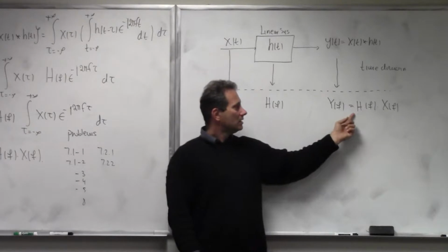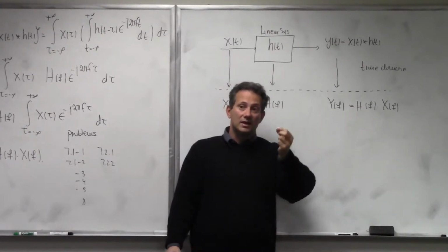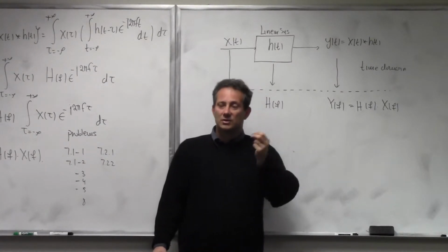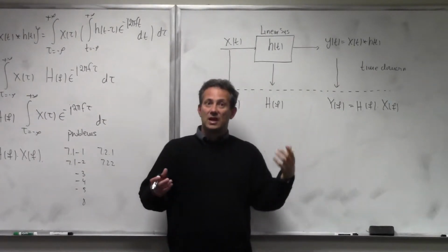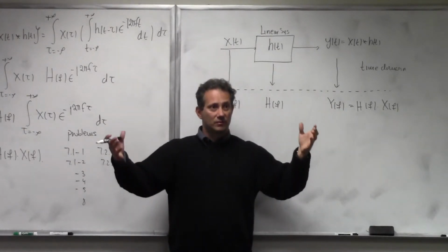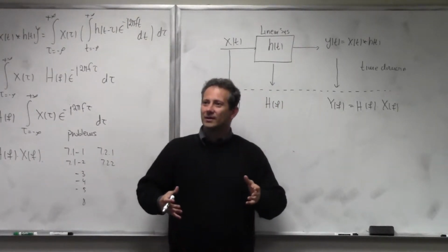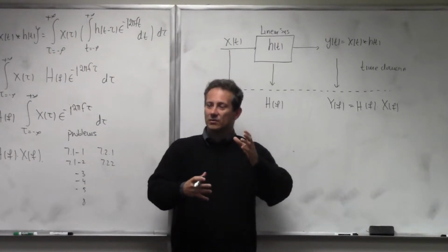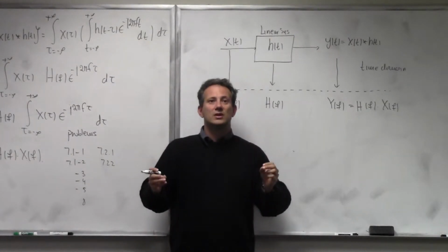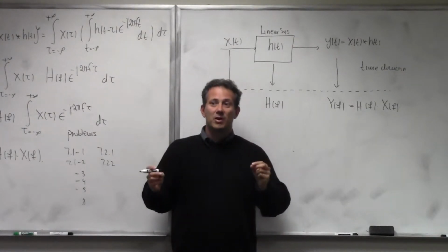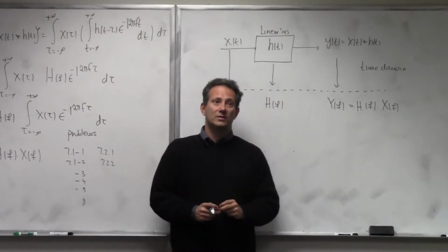And the effect is this multiplicative effect, right? This is a complex multiplication that says, take a sinusoid, change its magnitude, and change its phase. And then really, the spectrum of the output signal is the same as the spectrum of the input signal in terms of which sinusoids are there, but they're rearranged in a different way. They may have slightly different magnitudes and different phases. But there are no new sinusoids. That's a fundamental property and fundamental test for the linearity of a given system.